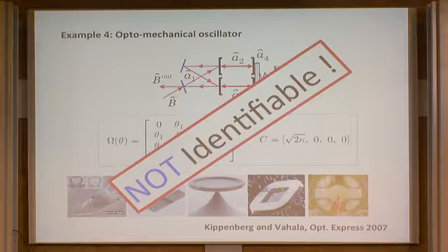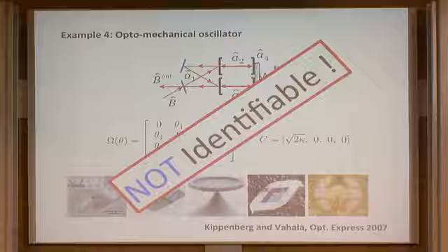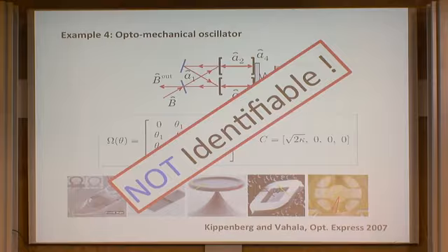Anyway, I think there are many linear systems, partial linear systems, that are identifiable, I guess. One issue is whether it's identifiable or not may not matter, depending on what you want to use the model for. If you want to use the model to design a feedback control system, then it only matters what the transfer function is.